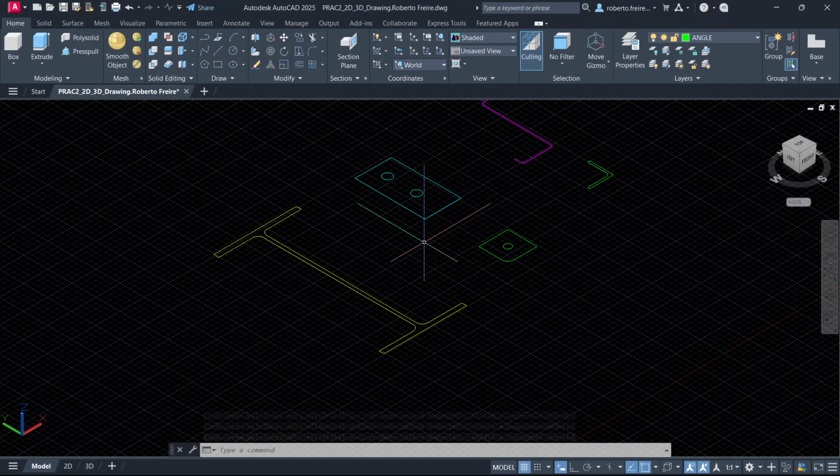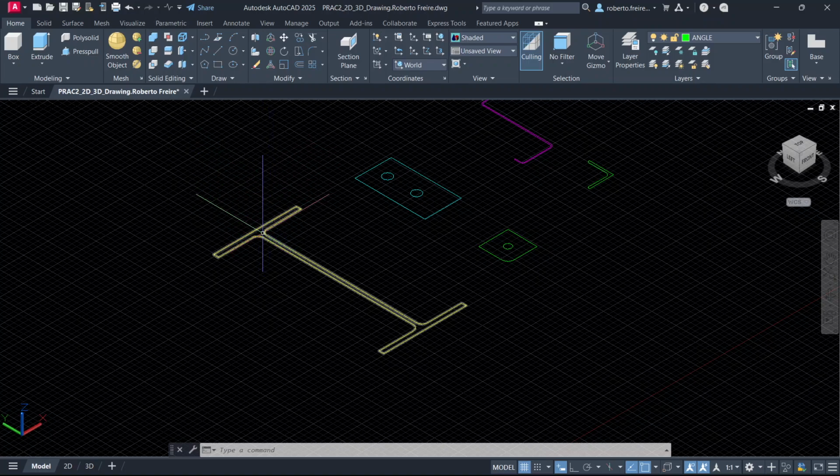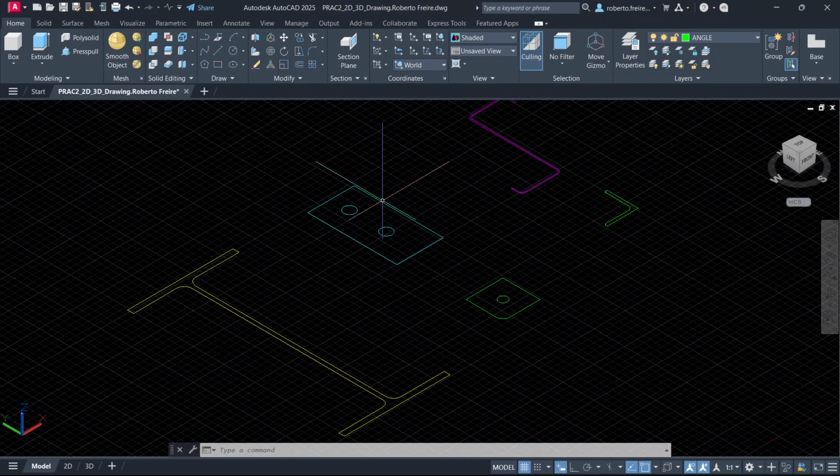If you don't do this step, you are not able to press pull the area, and you have some issues during the assessment. For example, for this one, this is the clip. So if you join this one, it could be a rectangle, but it's not gonna select the circle because the circle is not connected to the line, so it would be fine. Same thing for this one.